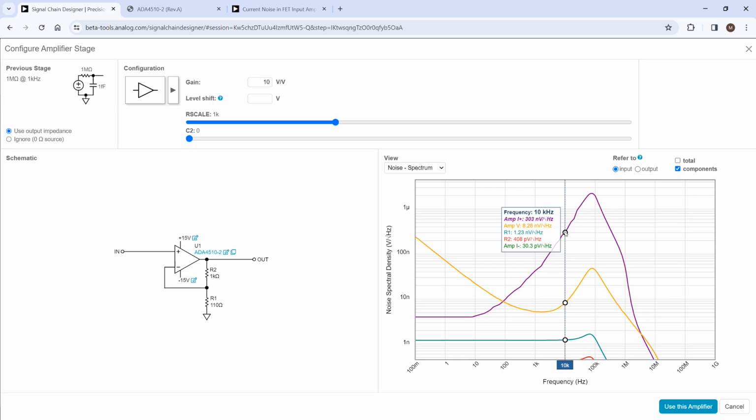We would typically put a number for low frequency current noise, but the general assumption was that, hey, FET input current noise is so low, we don't really need to mess with it. Well, it turns out that there is this ramp at higher frequencies, and occasionally it comes into play. A lot of times you'll have enough capacitance at your input and it won't matter, or you're rolling it off with filtering and it won't matter. So a lot of times it still doesn't matter, and remember, you're starting from a very low base. But there are occasionally times where it does matter, and so we have started putting it in our data sheets.